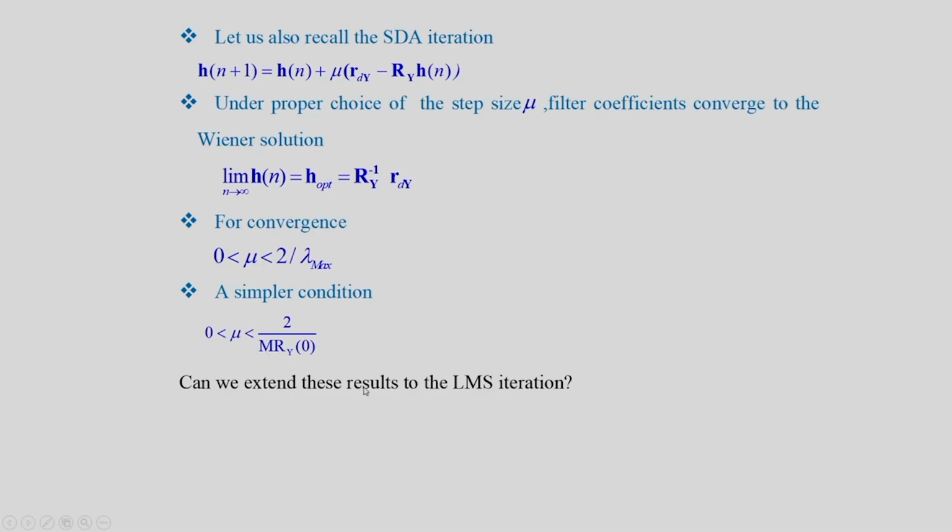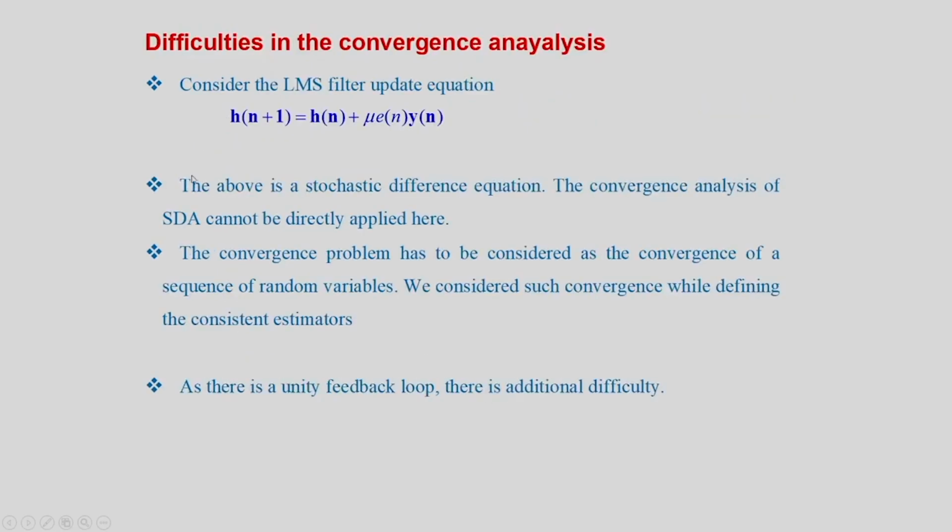Can we extend these results to the LMS iteration? Let us try to answer this. Consider the LMS filter update equation h(n+1) is equal to h(n) plus mu times e(n) into y(n). As it is a stochastic difference equation, the convergence analysis of SDA cannot be directly applied.